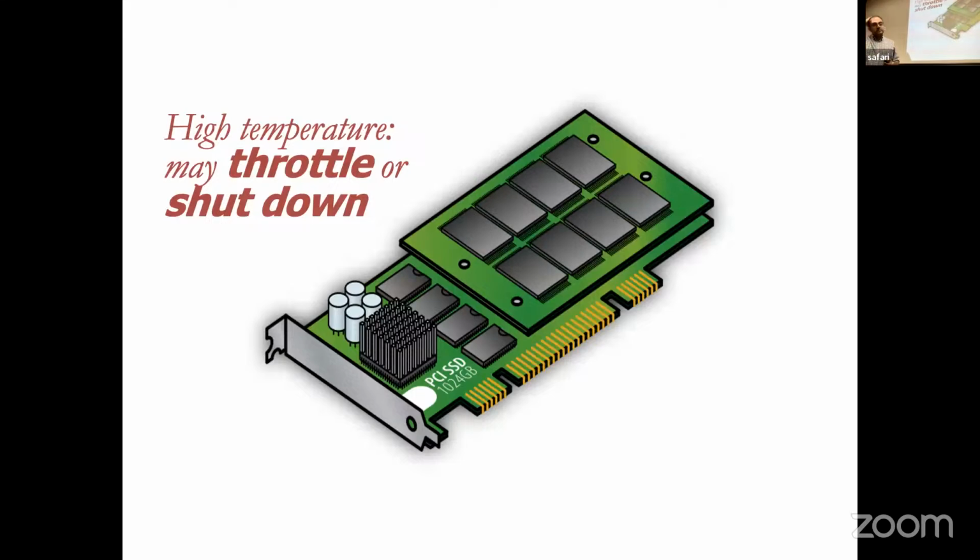But there are some techniques to avoid that, which is to throttle accesses. SSD can throttle accesses, reducing the bandwidth just to lower the temperature, or the SSD can completely shut down. That has some performance overhead, for sure. But it will reduce temperature, and it might make sense because you can reduce the number of errors, as a trade-off analysis.